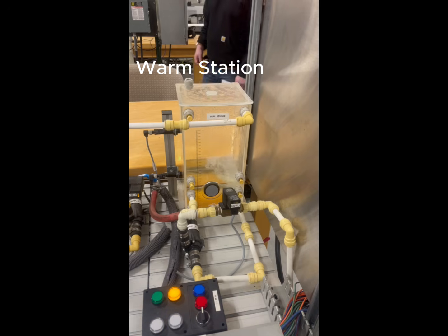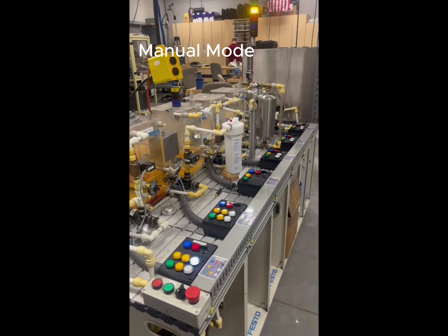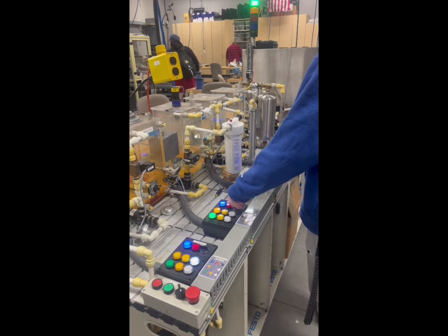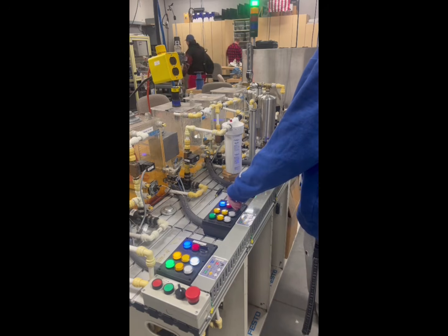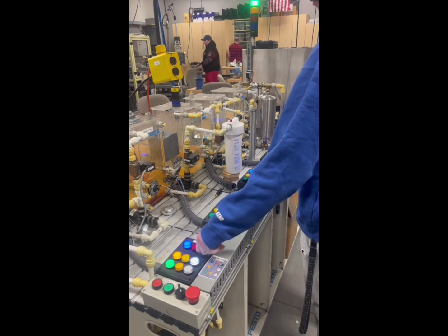And finally, the warm storage tank will refill cold storage whenever it's at a good level and cold storage is calling for more water. There is a manual mode operation with this station too. All I would need to do is enable the system and flip the CB1 selector switch to manual, and there is individual manual drain and fill knobs on each station too.